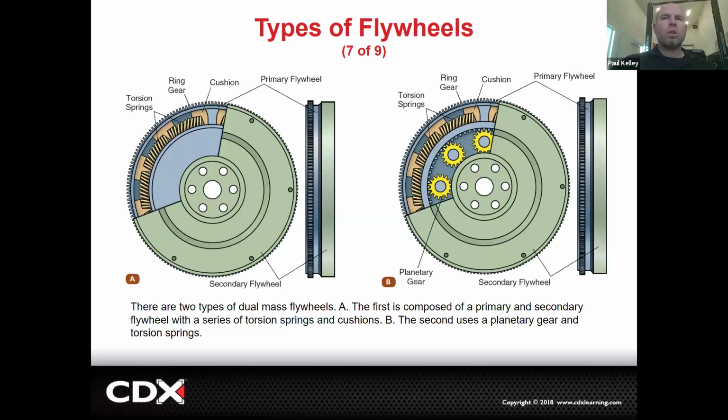Okay, so we're basically absorbing a bunch of those engine power pulses in the dual mass flywheel. And that's why a lot of times they'll call this the ultimate engine dampener. You could have a harmonic balancer, right? And that thing's kind of heavy, and that makes it so it sort of absorbs the power pulses. But if you notice, a lot of the newer stuff, they have smaller and smaller crankshaft pulleys. Not necessarily smaller like this, but you look at it, it's really just a pulley. Whereas in the old days, it was a pulley with a big weight and some rubber and some stuff. That was to absorb the power pulses. Now it's more of a basic, simple crank pulley.